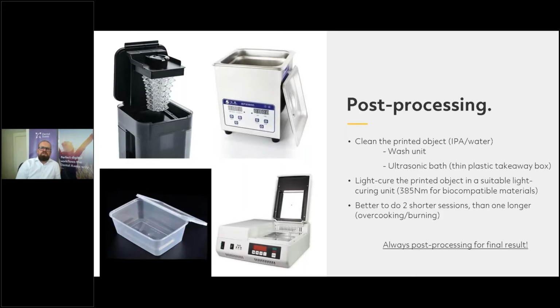We had a successful print, but what are we going to do then? We had a successful print, took it off the print platform, cleaned the print platform, but the next step is how do I make sure? So with a spatula, clean it, wipe it with IPA.